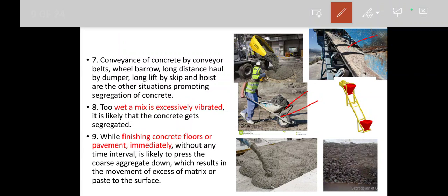And also it should not be too wet. When the concrete is too wet, if you do excessive vibration, what will happen? Here you can see the bottommost picture, the coarse aggregate alone has settled down, and only the cement paste is on the top.